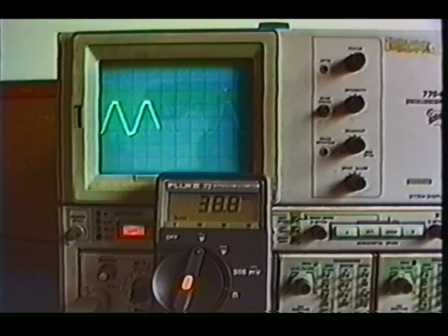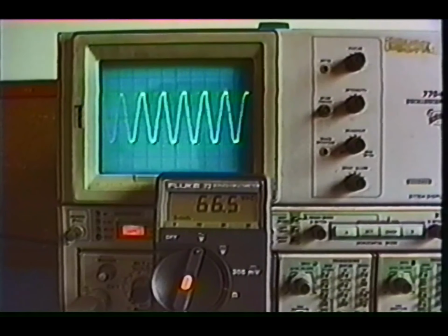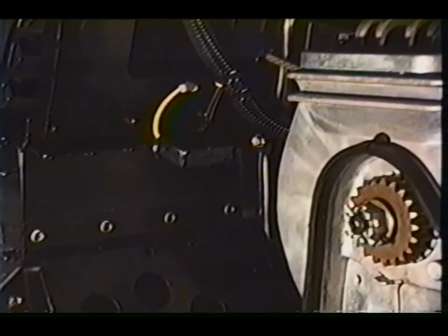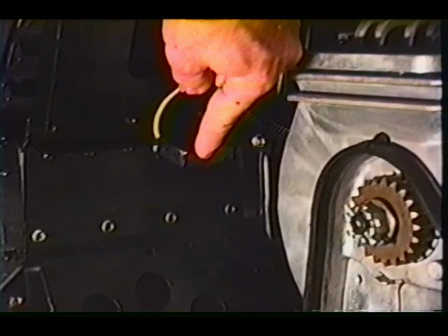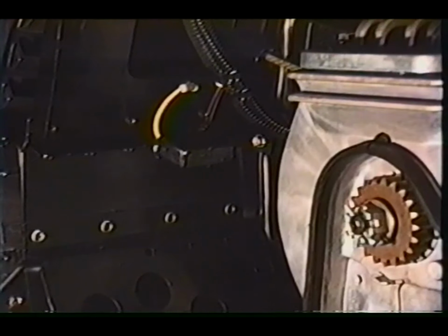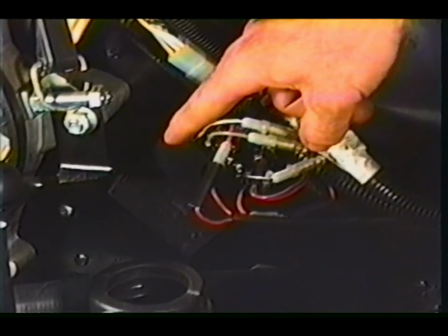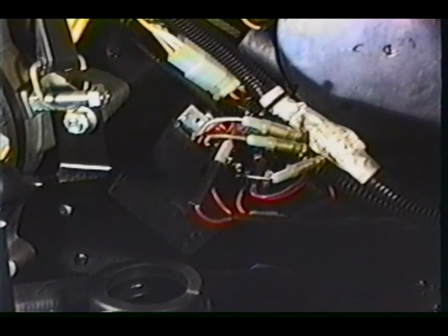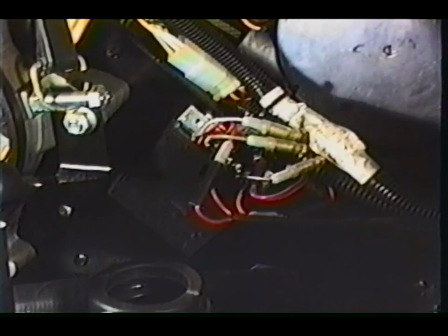AC voltage increases with RPM. To prevent damage to system components, we must regulate alternator output to about 14.5 volts. In an AC lighting system, as used on our snowmobiles, the regulator diverts as much voltage pressure as necessary to ground in order to keep from overloading system components. Think of the regulator as an electrical pressure relief valve. The DC regulator supplies the rectifier with as much AC voltage as necessary to maintain a DC supply. This is around 14.5 volts.